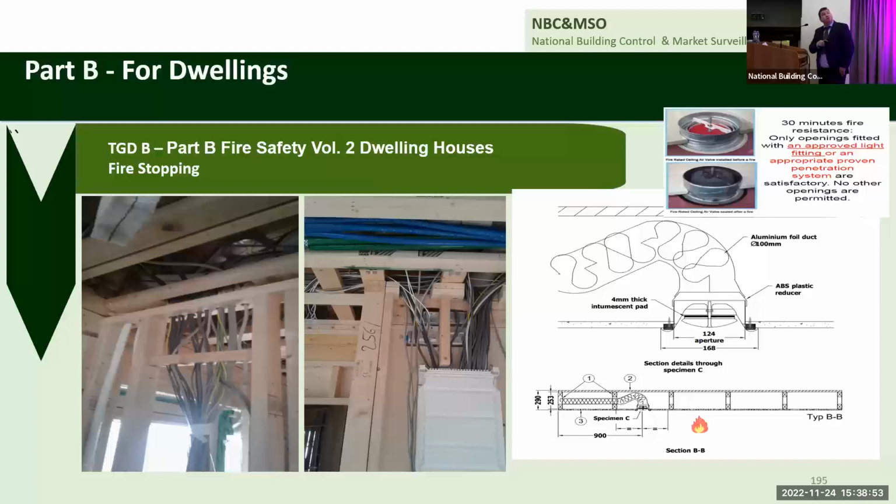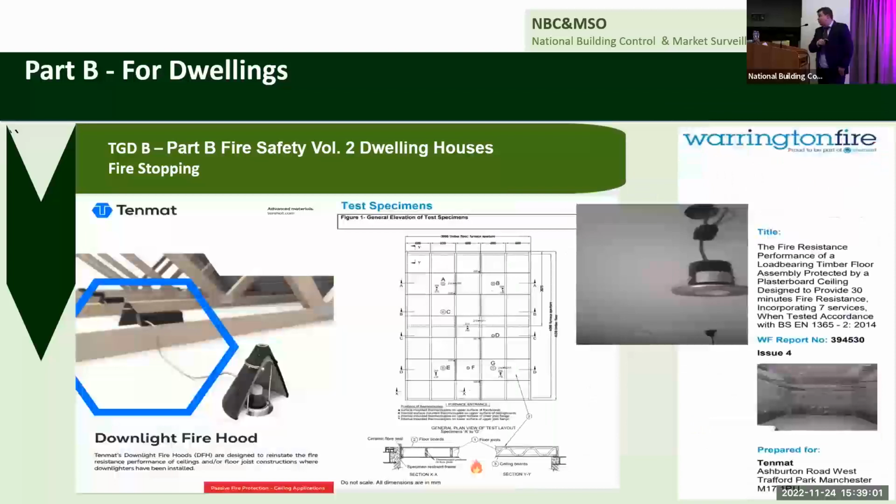This is a better detail here, but they need to come back and use a mastic seal here. That's actually compliant with the cables as well. That won't heat up and burn or cause a greater issue.